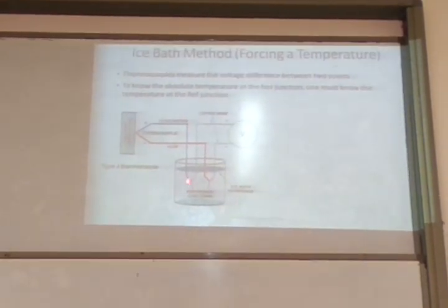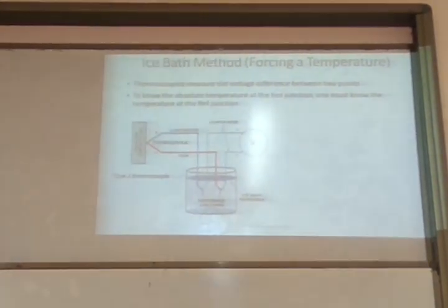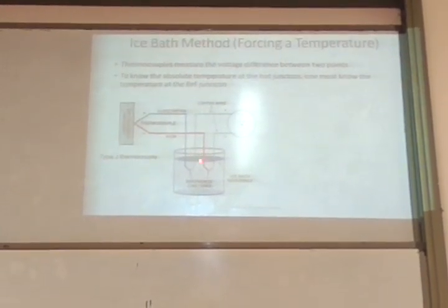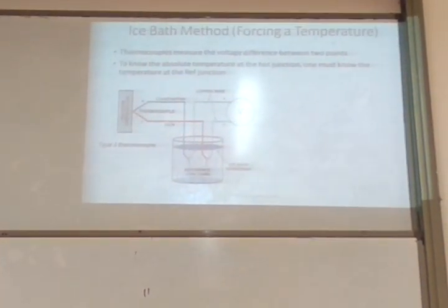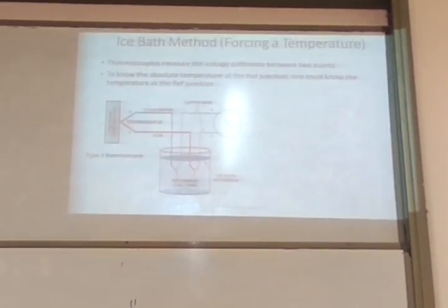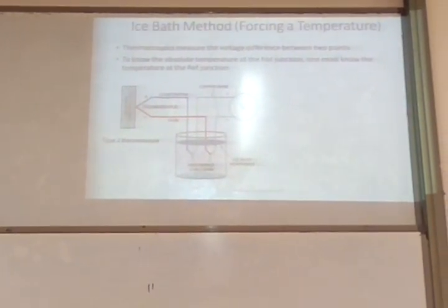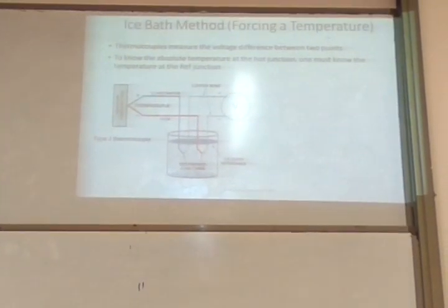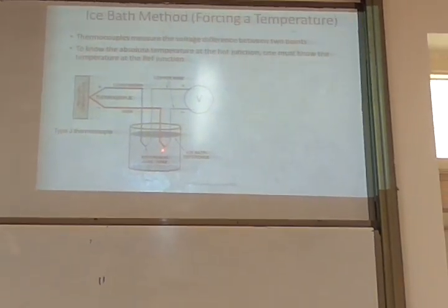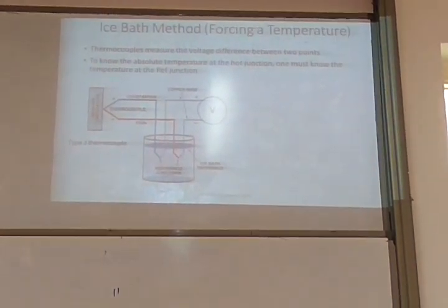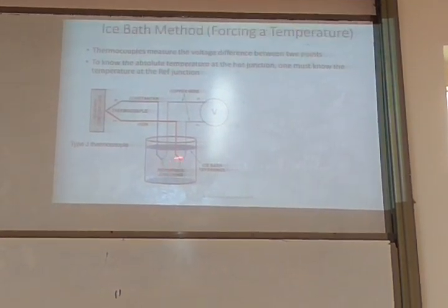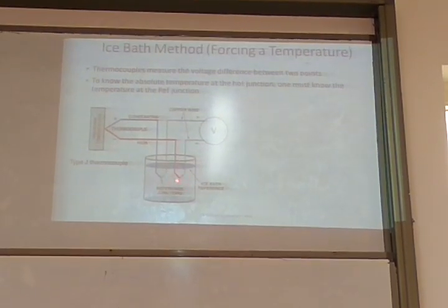As long as you bring these junctions to the same temperature, even though this iron and copper are also dissimilar, that will not create any problem. There are 5-6 thermocouple laws that we are not covering. Go through them. Those laws describe that even if these two are different materials, that will not create any additional EMF in the circuit, because these two pairs are all at the same temperature.